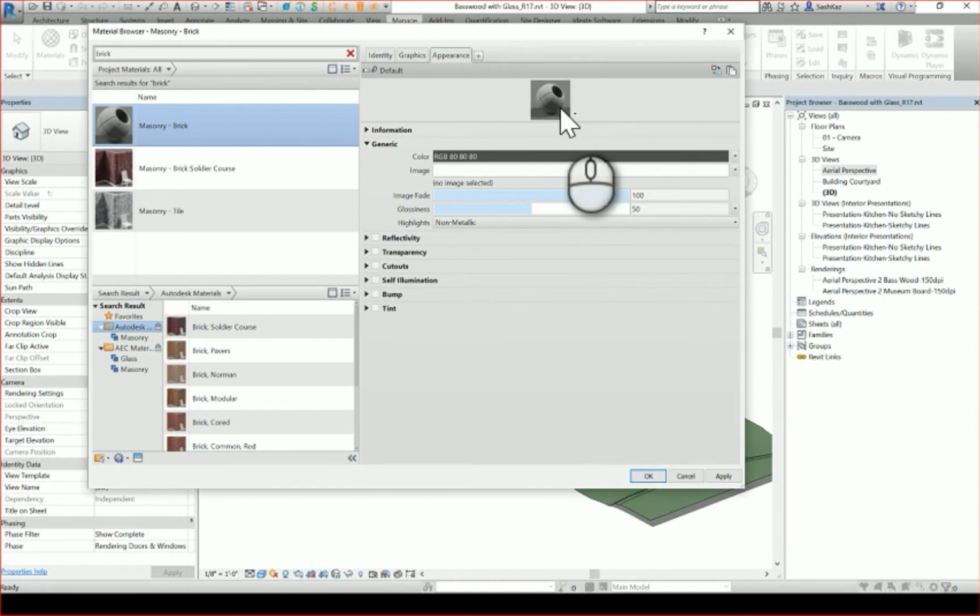And if you're not aware of this, up here, where there's a hand that says 0, be very careful. If you ever duplicate materials, you are not duplicating the asset. Remember, that brick could be used for other materials. If you need to tweak the settings and have brick 1 and brick 2 with a slightly different look to it, you need to duplicate the brick asset, okay? Or this default asset in this case. The reason why is that hand means it's being shared with however many materials it says up there.